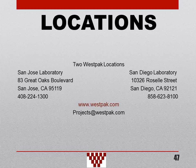So definitely you could monitor an ISTA 2A test, but it actually depends on your units. If you have a pouch and a medical device and you have 10 units in your little box here, we could monitor it, but the results that you get might not be consistent, because your pouch on one end might see something different than your pouch on the other end, as opposed to the pouch in the middle. But if you're shipping something like an electronic unit that's just one single unit, with a designed package system with foam, then the answer is definitely yes.